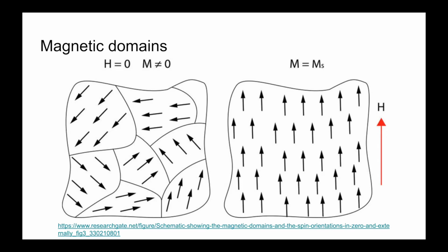In electric circuits, we usually talk about electrons flowing, like there's something that physically moves from one conductor to the next. In magnetic circuits, this is not exactly the case. Instead, we talk about something called magnetic domains. The spin of each electron in the material acts like a tiny bar magnet, and when the magnetomotive force is applied, these bar magnets all align in order to create the magnetic field in the material.